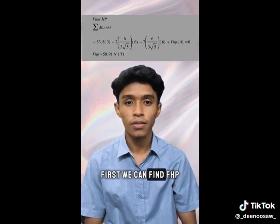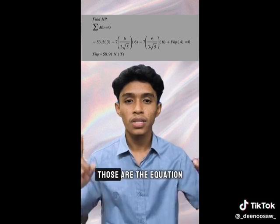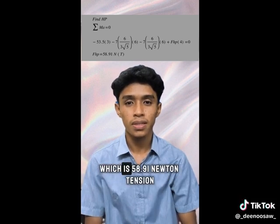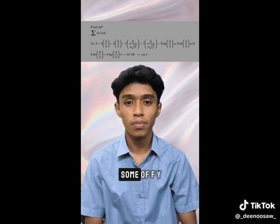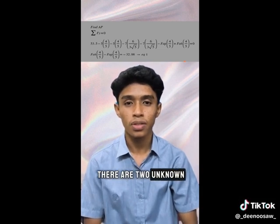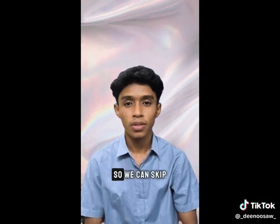First, we can find FHP by calculating moment at A equal to 0. Those are the equations. And then, we get the FHP value, which is 58.91 Newton tension. Next, we can find FAP by using sum of Fy equal to 0. But we notice that there are two unknowns, so we let it become equation number 1. So we can skip that for a while.